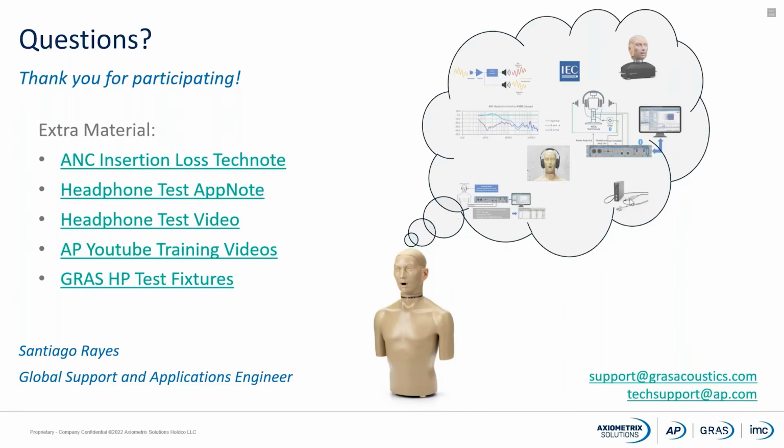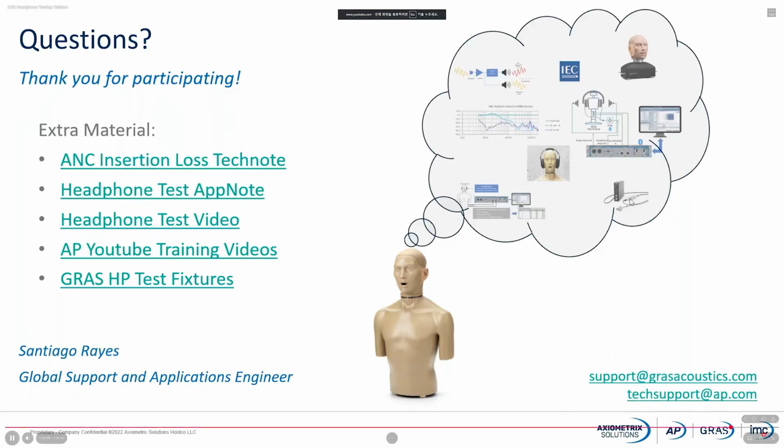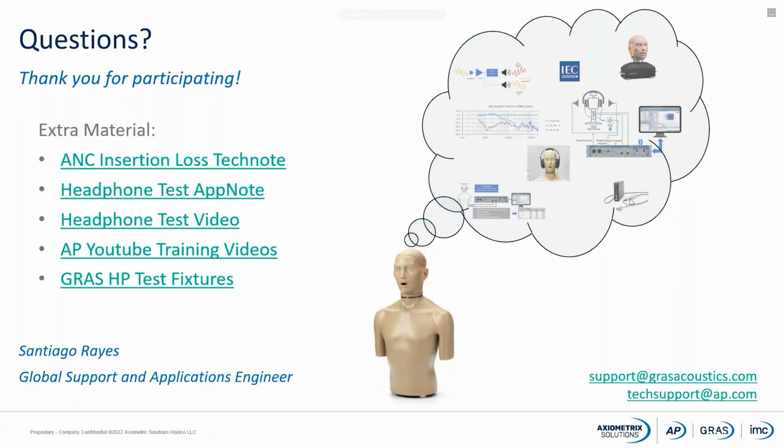I don't know exactly what you mean by that, but in headphone testing, we tend to perform multiple measurements of one device. We might place the headphones in place, we might remove them and place them again, and take a lot of different curves, and then we'll average the left result and the right results. We can take 5-10 measurements depending on if we're working on an R&D situation, if we're in production line testing, and so on. How much time do we have to test the device?